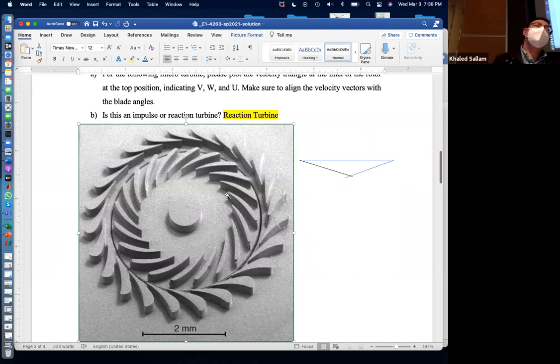Your gut feeling should tell you, well, because it's a compressor, and now we know the turbine was going this way, the compressor has to go the other way. But what's the other reason? So it's going to run counterclockwise, but what's the other reason why it should be running counterclockwise? The stator is a good reason too. If I turn it this way, the flow at the exit of that rotor will be going this way, and that stator will be perfect for it. But the other reason is also this.